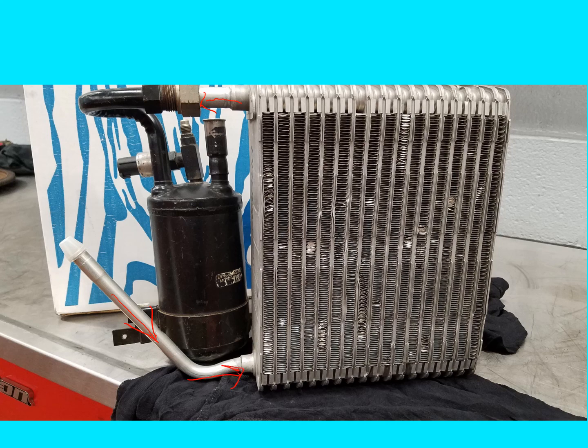At the bottom, low temperature, low pressure refrigerant flows in and across the bottom. And then about halfway up it starts to vaporize in the middle, and it's going to exit out the top as vapor. Now, if any liquid does come out of the evaporator core, it's going to get trapped in the accumulator, which is being shown here. So the liquid refrigerant would drop to the bottom. And this would be the outlet right here going back to the compressor.